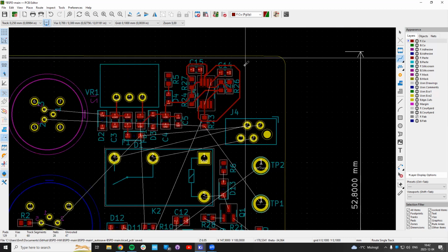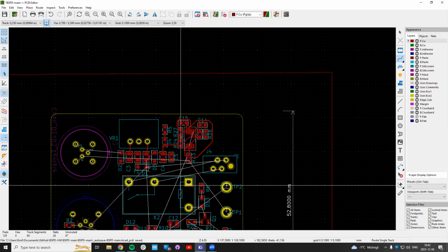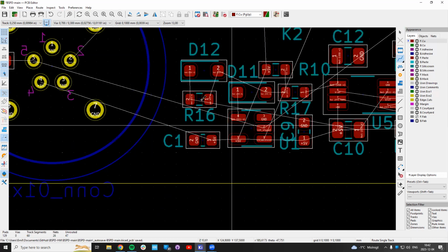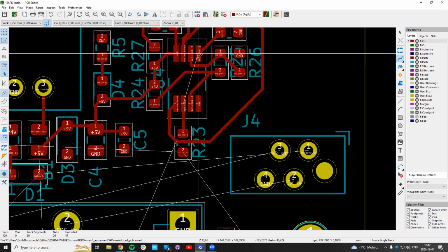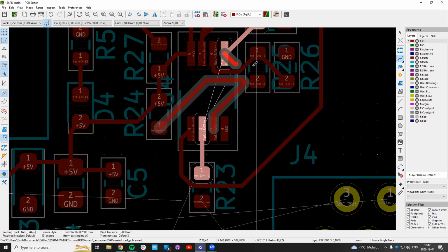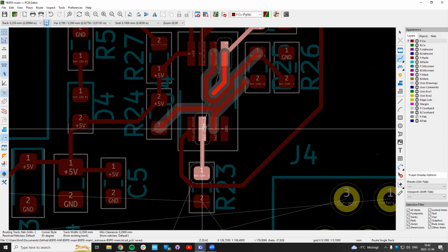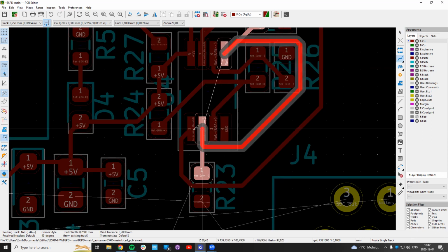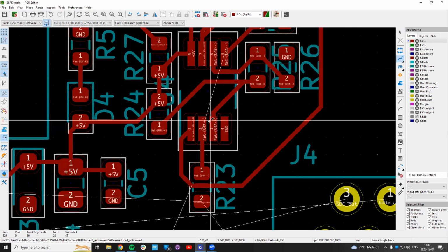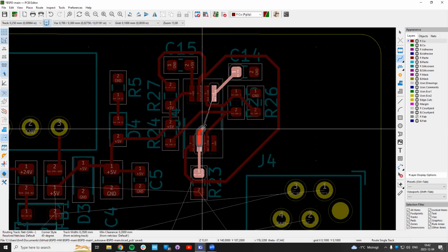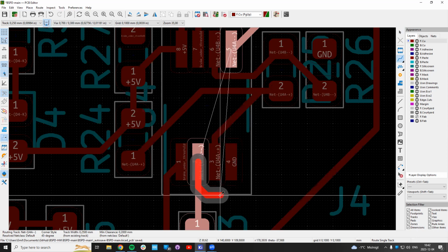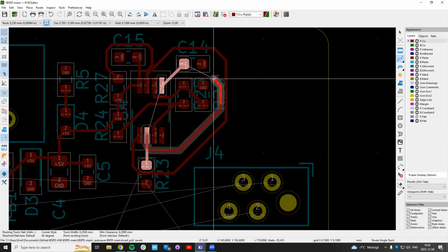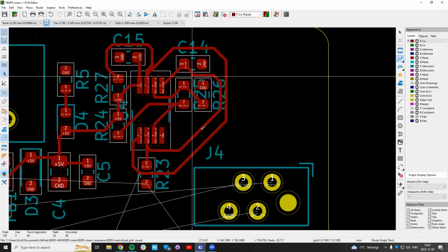And you know, you can add settings where if I want to route this, let's see, what's a good example? If you want to route a really long trace, okay, this one will be like that. You see how it kind of takes a while before it decides on a point. You can add different amounts of how much it tries to calculate the best route and such. It's a little bit strange, but you can find some cool settings to play around with if you want the tool to do more of the routing for you, basically. But yeah, leaving it as standard is also going to be okay.